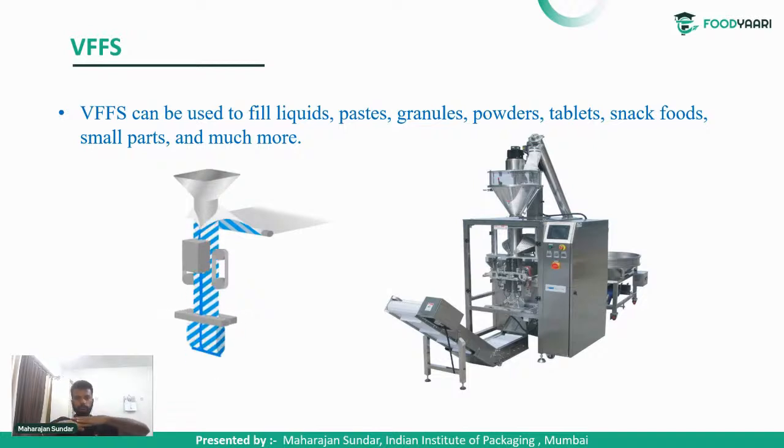Okay, after sealing the bottom of the package, the product will flow through the hopper, which is shown in the upper part. For example, 500 ml of milk will be dispensed and will fall through it, and because the bottom end is sealed, it is held inside the container. Then it will move down a bit so that the top of the product is also filled. While sealing the bottom of one pack, it will also seal the top of the other end. Then detachment will happen, and then distribution and arranging in crates will also happen.